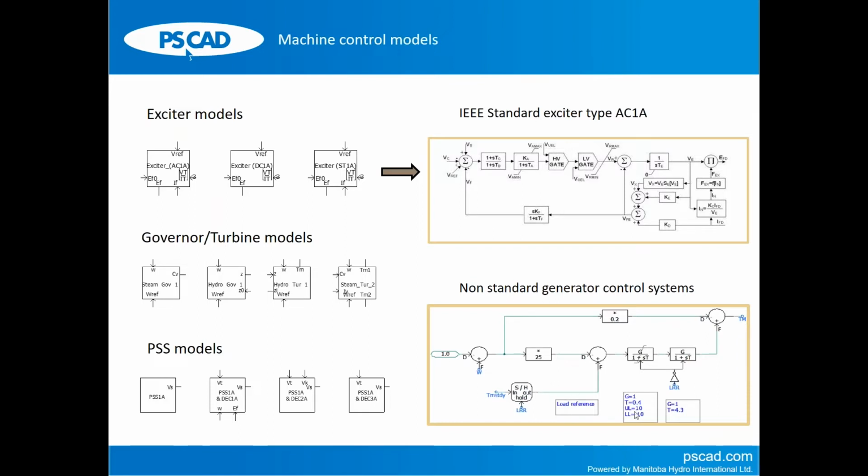So I'm not going to talk about back initialization today. We have technical notes and examples which we can provide upon request. It's not difficult. But for our standard models, the back initialization is pre-programmed, and if you tell the model the initial conditions you want it to operate at before you apply faults or something, the models will go through the pre-programmed back initialization routines and give you the expected steady output right from the start.